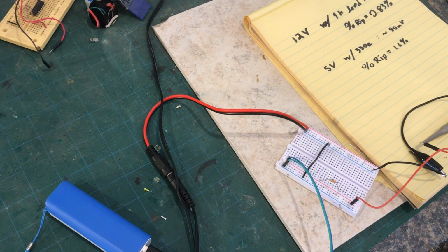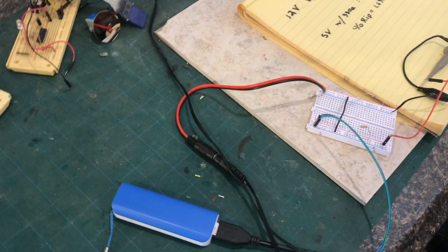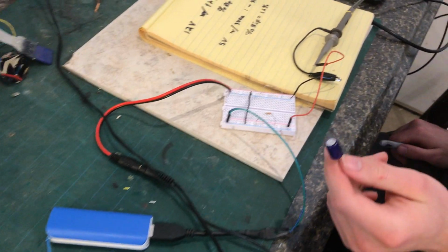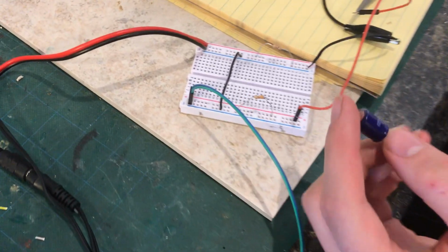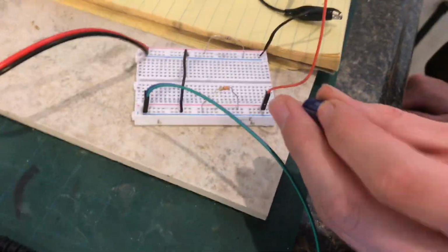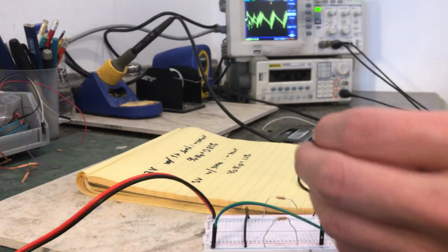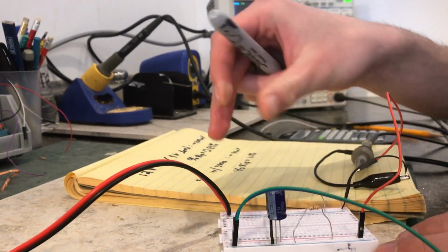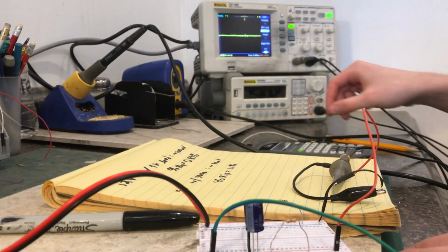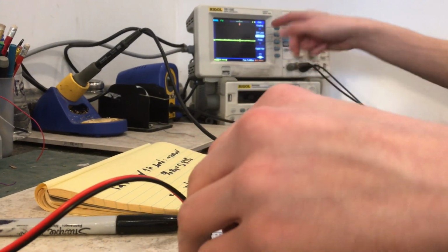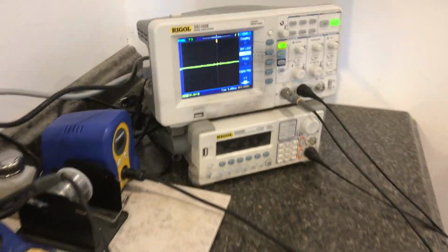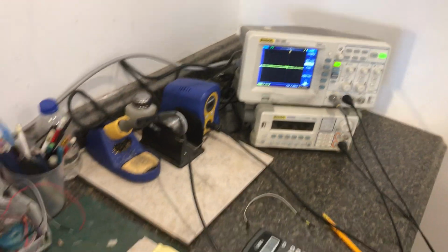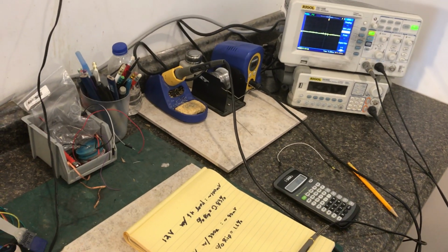So, how do we take care of this? We can throw in a huge capacitor, and that's what I'll do. We'll see what happens when we put a capacitor in. Electrolytics have polarity, gotta be careful with that. I put it into the 5-volt circuit, and you can take a look at the oscilloscope. I haven't changed the setting at all. There's without cap, that's with the cap. Big difference. Of course, it's a 1,000 microfarad capacitor.